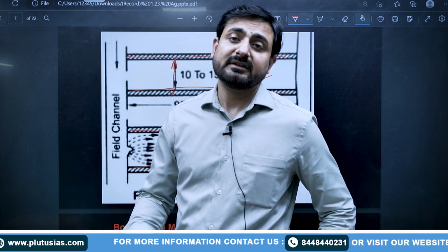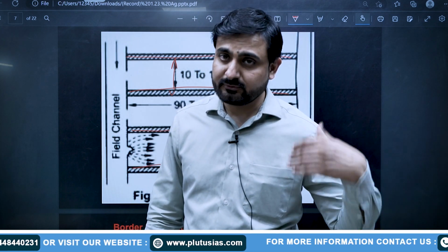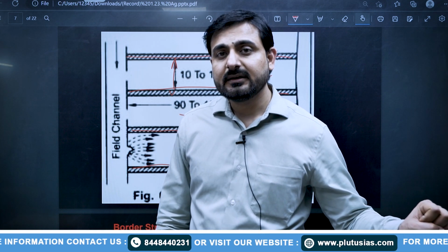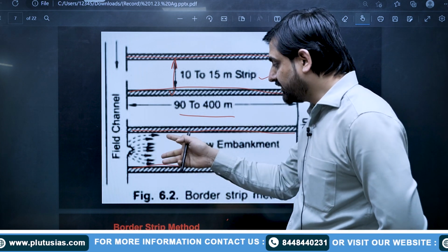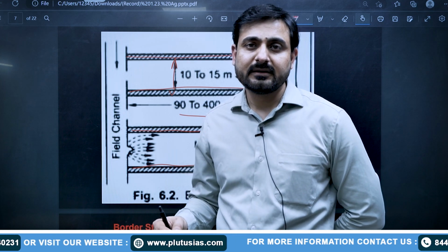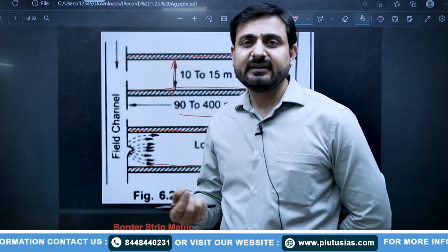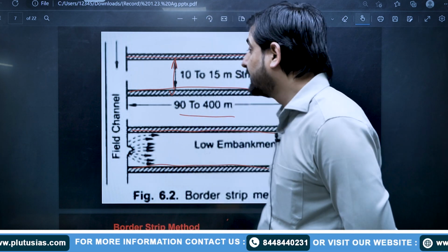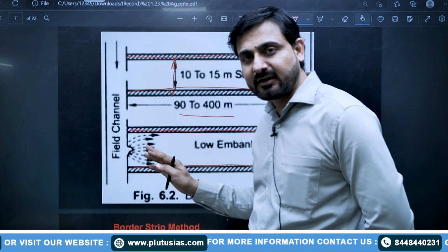But the border strip method is likely to be more helpful, especially for certain crops which require a high amount of water, maybe sugarcane, maybe paddy, jute, etc. This border strip method seems to be easier because you need to develop only the vertical strips here. The amount of land consumed by the bund is slightly less, most of the time, than in the check basin method. It is easier, but again, a lot of land is wasted around the bunds.